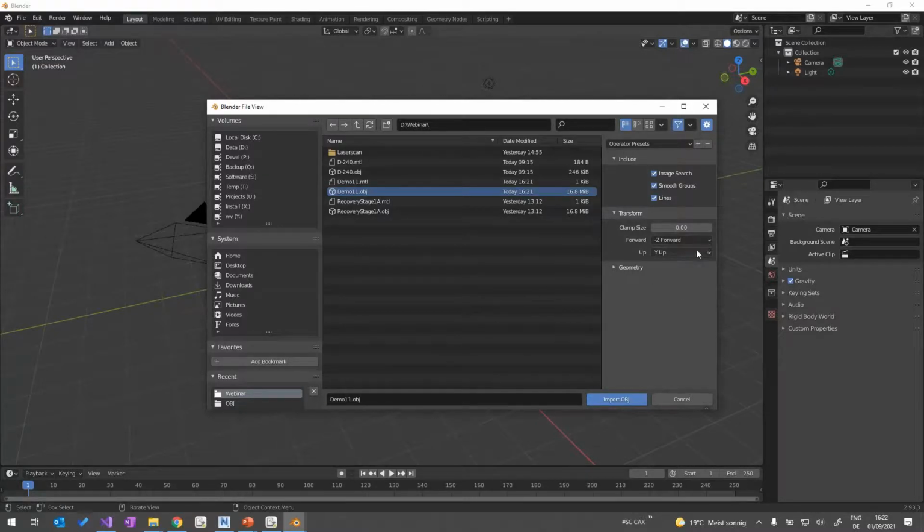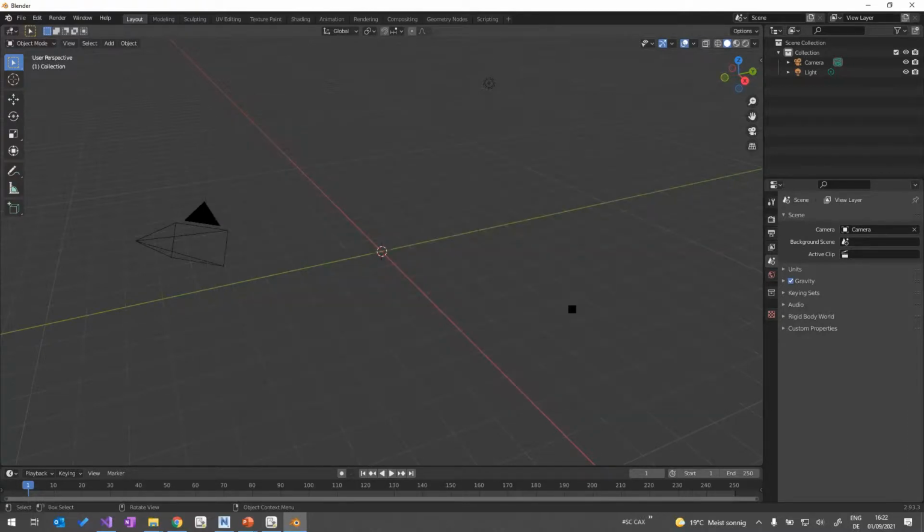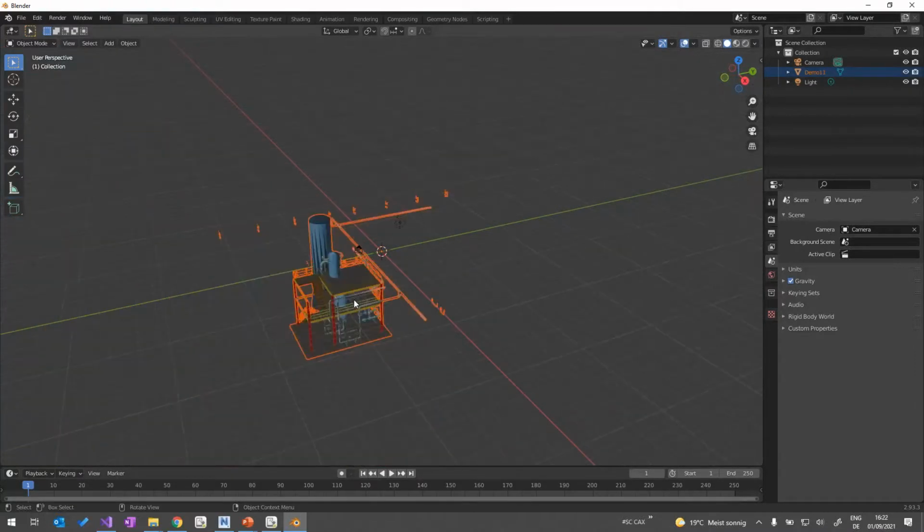When importing OBJ, you might need to specify the axis you want to use. So in my case, I did not swap the axes. Therefore, I will select Z as the up axis. But if I had checked the option to swap the axes, I would not need to change it here, okay? And now I can import this into my Blender,